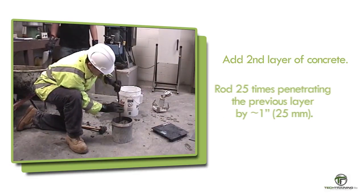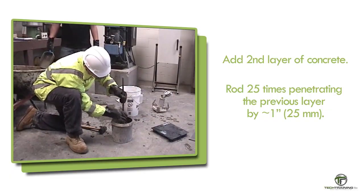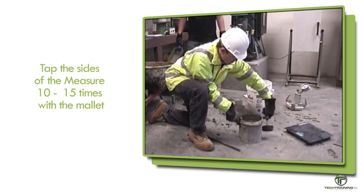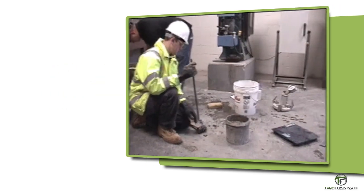We now want to rod the second layer 25 times. The second layer is rodded throughout its depth, penetrating the previous layer by approximately 1 inch, or 25 millimeters. Once again, tap the sides of the measure 10 to 15 times with the mallet, using such force as to close any voids left by the tamping rod and to release any large air bubbles that may have been trapped.